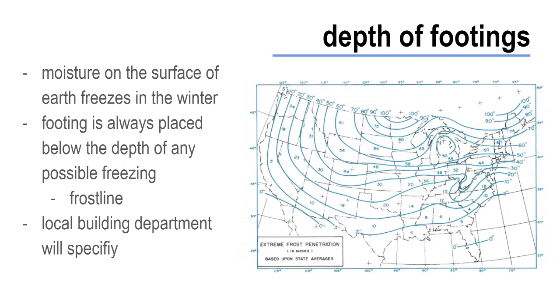To eliminate this problem, the footing is always placed below the depth of any possible freezing, which we know as the frost line.